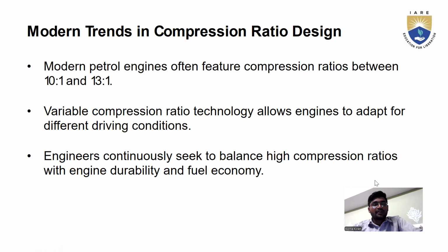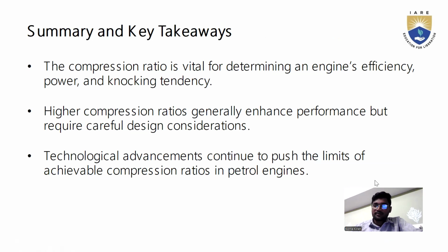And modern trends in compression ratio design. Modern petrol engines often feature compression ratios between 10 to 1 and 13 to 1. Variable compression ratio technology allows engines to adapt to different driving conditions. And engineers continuously seek to balance high compression ratio with engine durability and fuel economy.